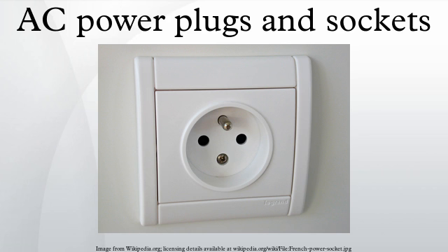CEE 7/16 Europlug. This 2-pin plug, rated at 2.5A, is popularly known as the Europlug. The plug is unearthed and has two round 4mm pins, which usually converge slightly towards their free ends. It is not rewirable and must be supplied with a flexible cord. It is defined by CENELEC standard EN 50075, flat non-rewirable 2-pole plugs, 2.5A 250V, with cord, for the connection of Class II equipment for household and similar purposes,